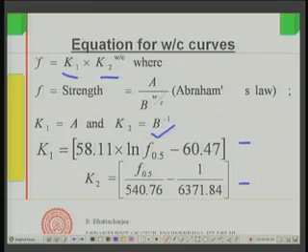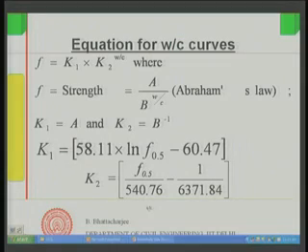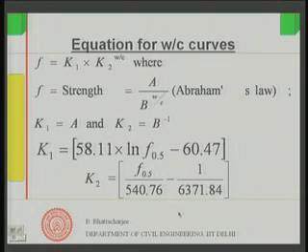So, this can be easily worked out in an Excel sheet also, without going through the curves, because these days it is very easy to work on Excel sheets, and through this equation you can find out. Well, this is how we can determine the water cement ratio, first from the curves and then from the same equations.